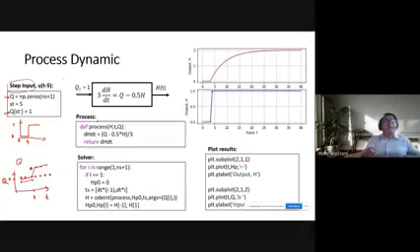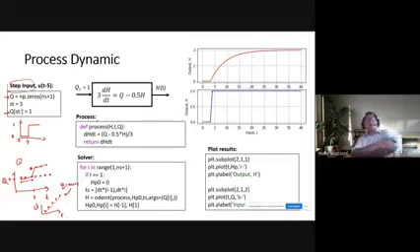Let's say you have a ramp, then you need to create your own ramp signal. So meaning that you know the value of Q, and then this is your T, then you need to assign something like this. Yeah. Let's say if you have a ramp, then how do you get this function? Maybe y equals mx plus c. For the formula, then you can put it inside here. Right. This is if you want to study the process dynamic according to the forcing input. So the rest is still the same, just like this for the process, and the solver is a little bit different.